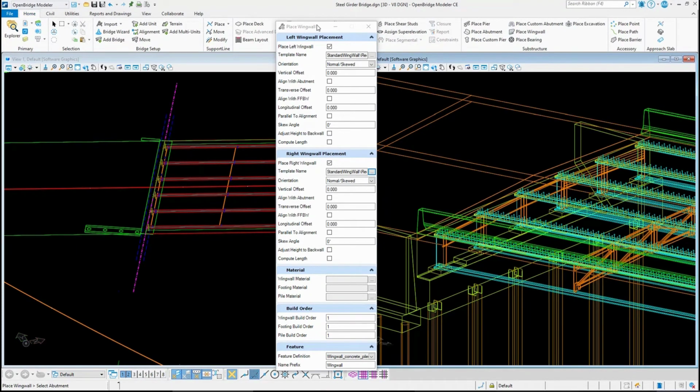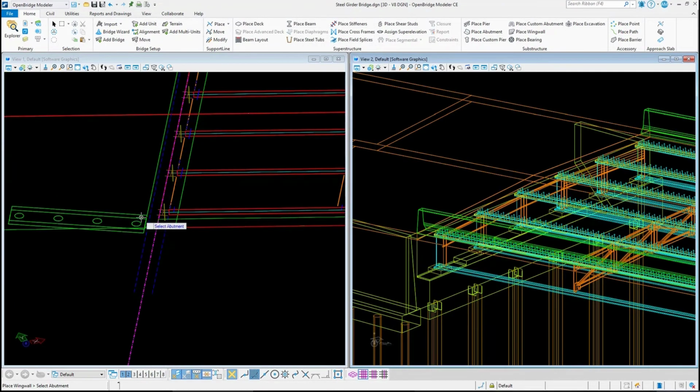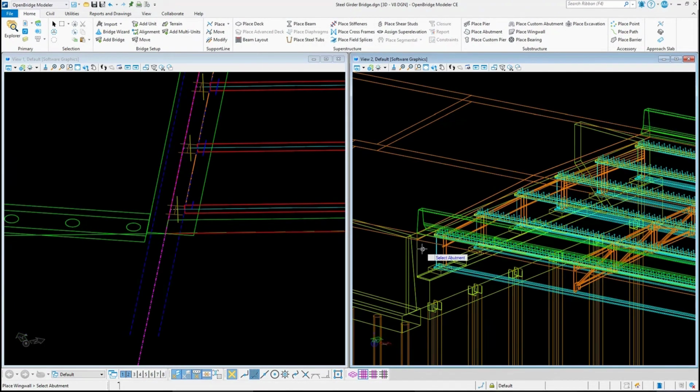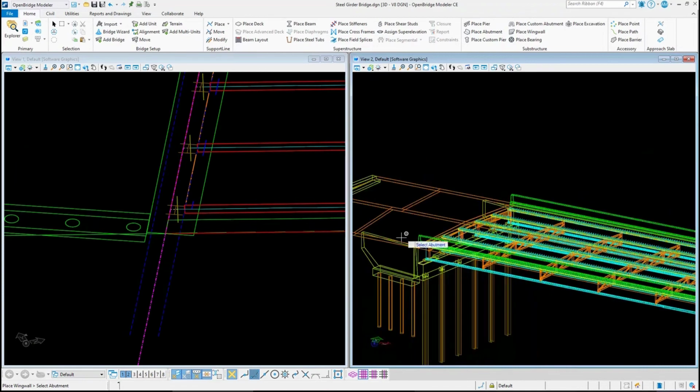The challenge that is happening with many DOTs when we place these wing walls is on the connection, right? They treat the connection way different. They put hinges, corner blocks, sometimes they call it. So every DOT does its own version of a wing wall or an abutment itself, right?